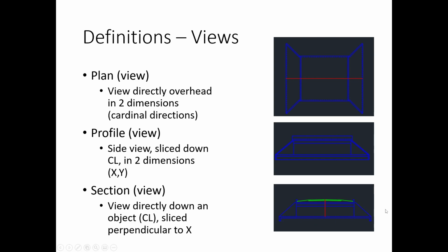So the water flow is actually still kind of left to right, the same as it is in the plan view. So this is just what the inside, essentially, of this box looks like. The green here is just the roadway going over the top. And then the water would flow through here. But it's at a specific station, basically slicing it in half as you move along the center line. And it's basically perpendicular to the direction of the center line. So those are our three primary views that we use in engineering, and kind of represent some of the survey needs we'll need as well.